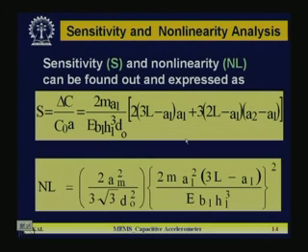Now, the sensitivity and non-linearity are another two parameters which we are also interested in, because in our design specifications non-linearity has been expressed as less than 1% of the full scale, and sensitivity is 0.02 G. So, for that also we have to calculate the sensitivity as well as non-linearity of the devices. Analytical expressions for those are given in this view graph here.